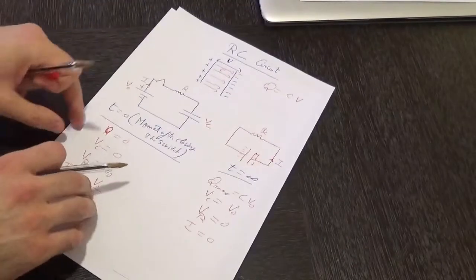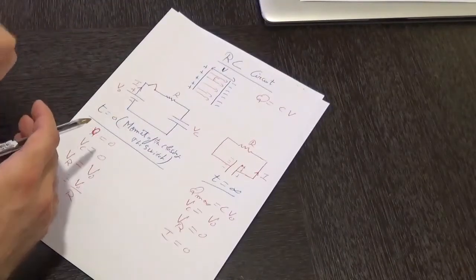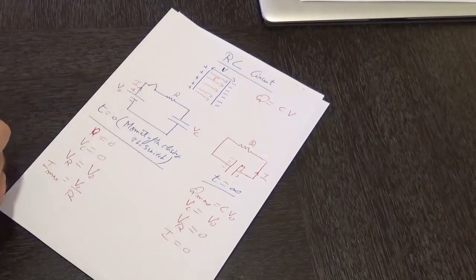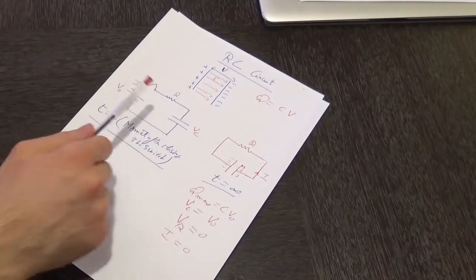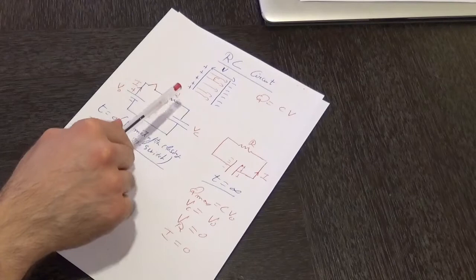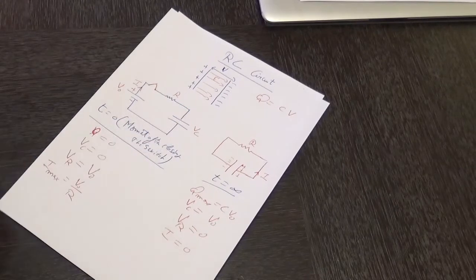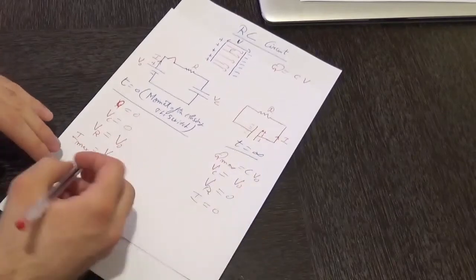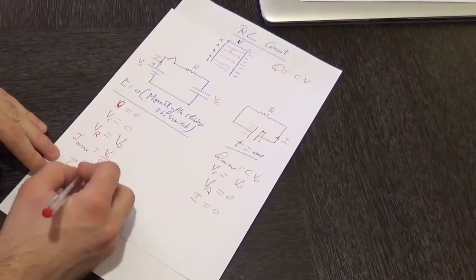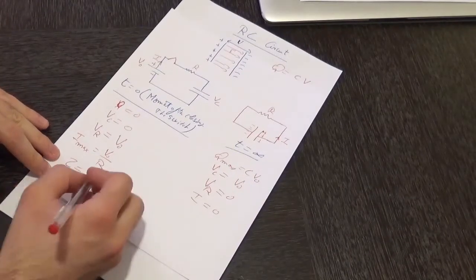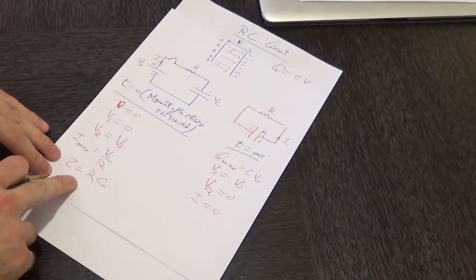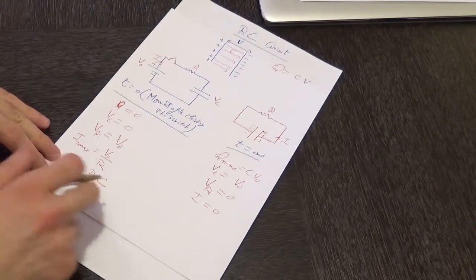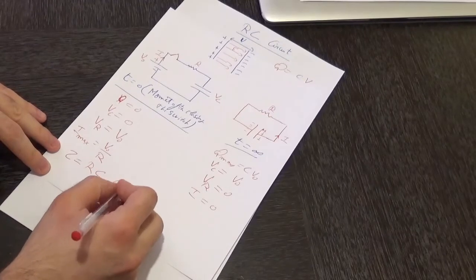But what is actually impacting that time constant tau in the case? That time constant tau is being impacted by the parameters that make up that RC circuit. So these parameters are what? They are the resistance of that resistor and the capacitance of that capacitor. So theoretically, if you want to find the time constant tau, it's given as the resistance of that resistor R times the capacitance of that capacitor. So tau is equal to RC, and the dimension of tau in that case would be seconds.